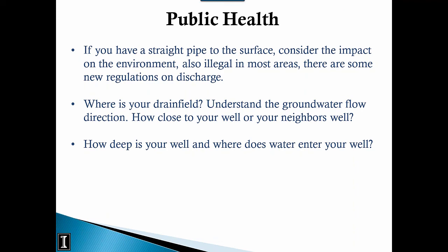But that also means that you're only 13 feet from land surface, so anything that infiltrates into the ground can also get into your well, and that comes into play the same for your septic. If it's that kind of geology, then there's more chance that some of the water coming from your septic system may not be as treated and may be able to get in. It's just more of a risk. That's just the thing to keep in mind.